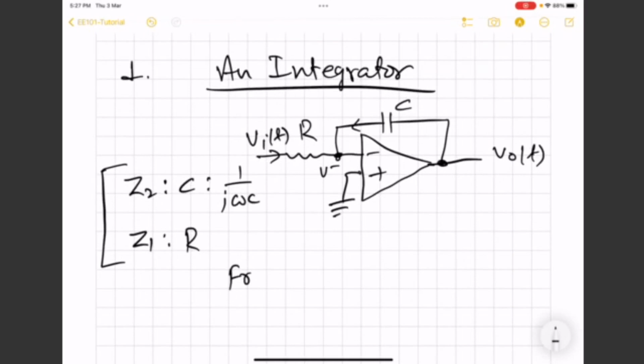That is why one has to see that there is a flow of current, not just connection. And if this is the case here, then Vi has to be time varying. For DC, ultimately this current is going to be 0 because the capacitor will charge and it will not allow any current to flow through it.